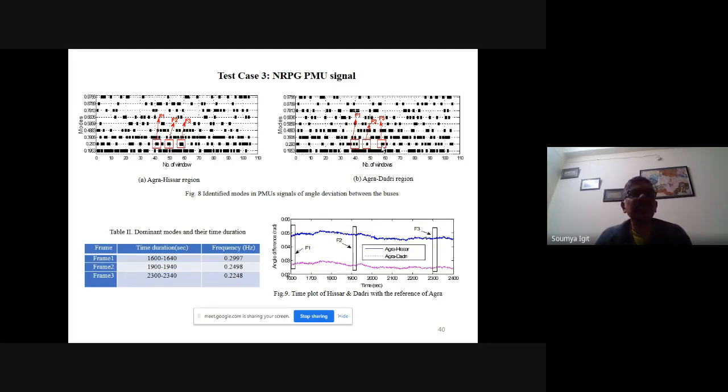For instance, you are talking about relay coordination for the active distribution network with respect to the bidirectional power flow, your coordination time interval and exchange of information between the two relays and optimum operating time of the relay as far as relay coordination is concerned. With the inclusion of different renewable energy resources, it doesn't work fine as far as the normal conventional way of relay coordination being carried out.